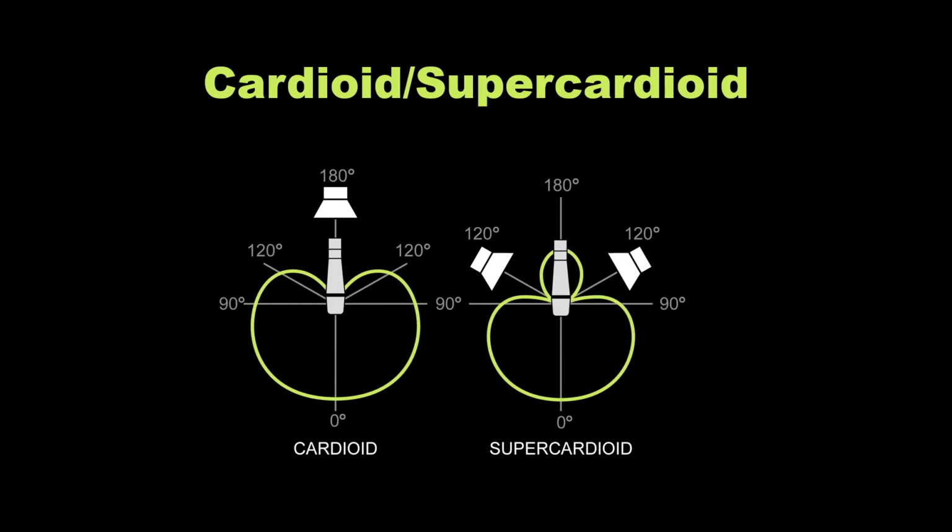And the Shure Beta 58, for example, is a supercardioid pattern microphone that I've heard sound engineers refer to as, quote, the feedback 58, meaning that they think it's more susceptible to feedback than an SM58 is. Actually, because it's a supercardioid pattern, which is tighter overall, you should get better gain before feedback with a supercardioid. Why does this happen?